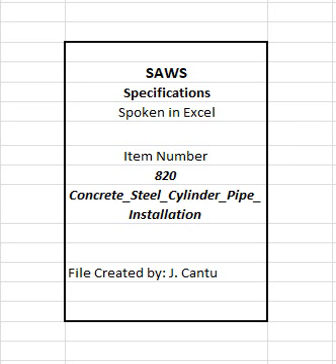C. Certification product is suitable for use in contact with potable water. 17. Submit proof of certification for welders. 18. Cylinder and joint ring assembly. A. Inspect physical dimensions and overall condition of joint rings and cylinder/joint ring assembly to verify compliance with requirements of AWWA C301 or AWWA C303.